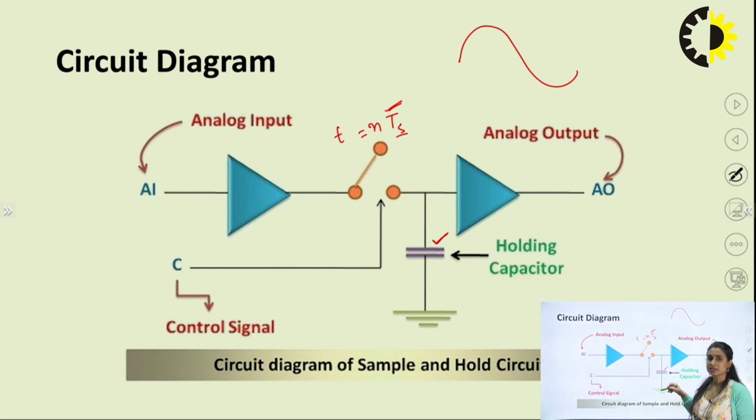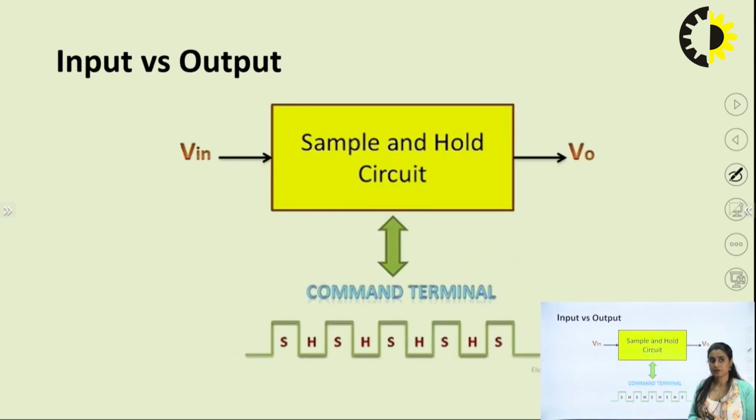And while discharging, the next charging should start after the appearance of my next sample, which should be delayed by Ts time duration. So I can justify it with this, right? So this circuit works for generation of sample and hold waveforms, right? So when I give input, the sample and hold circuit must give V output, and I can say at this voltage this is called sample, this is hold, and sample, then hold, sample and hold.